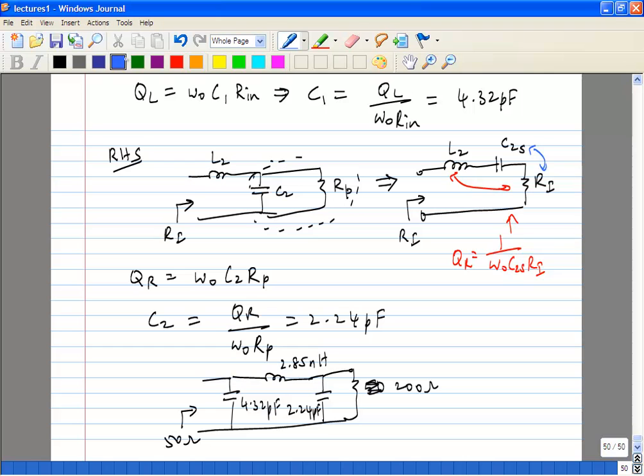Yeah, in a sense, suppose you are working for that broadband signal. This particular signal is matched to that 200 ohm for that particular frequency. Now, if our match is poorer, when you say the match is poorer, do you mean a lower quality factor or a higher quality factor? You mean a lower quality factor, I assume. Yeah, meaning it is not matched. Suppose I have a bandwidth from 2.2 gigahertz to 2.4, and my signal is matched at 2.2 gigahertz, where it is entirely matched. And I have a quality factor such that at 2.2 it doesn't match properly. You can have that return loss problem. Exactly, that's right. Which is why you want to define your Q also. That is the main reason why you want to define your Q.